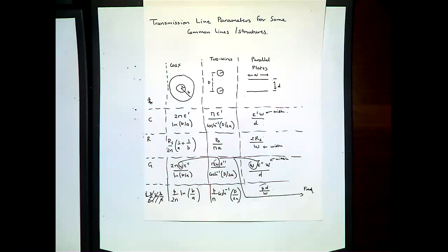We did that briefly in the first lecture where we had a cavity, and I showed you that if you produce a cavity, because of the Maxwell-Ampere relationship and the displacement currents, every set of parallel plates not only has a capacitance, it also has an inductance. It's fundamental whenever you set up such a system and excite it. And essentially it also sets up a self-resonant frequency for that structure, which tells you that there is a maximum frequency at which you can operate it.